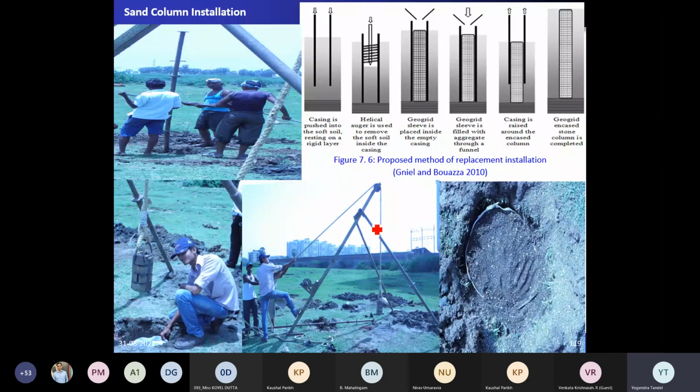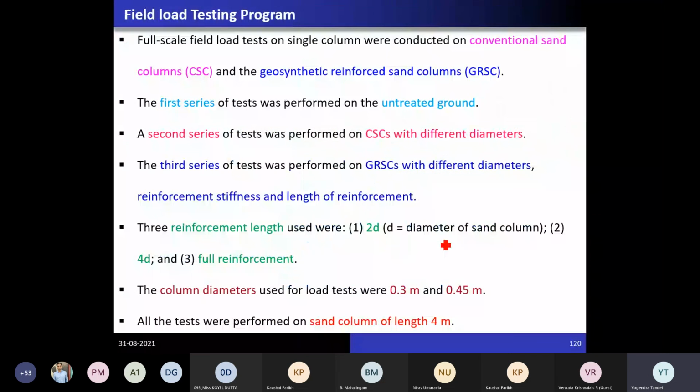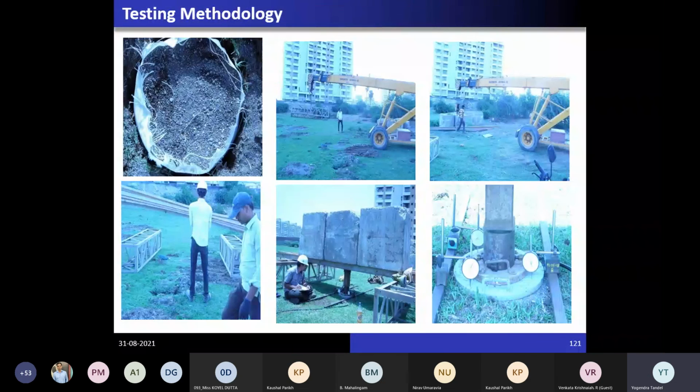Okay, and here this geotextile is actually being kept at a particular level. When you insert the geotextile inside this casing pipe, at the upper level it should be tied, otherwise it will sink into the ground. As you compact, it will take the form of this circular cylindrical shape. So these are just certain background related to the loading arrangement and all this displacement.